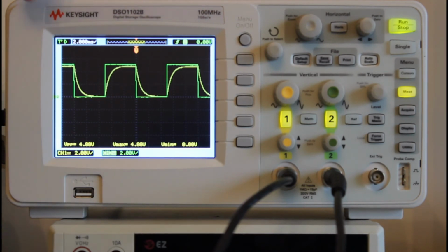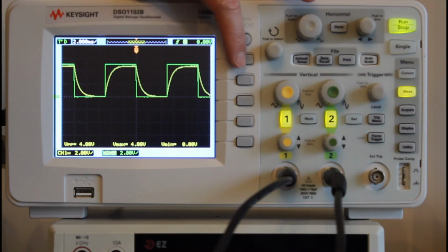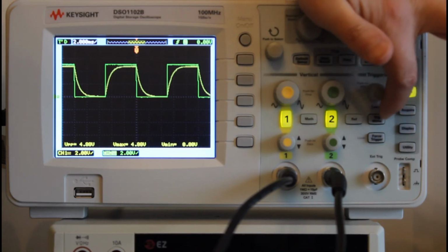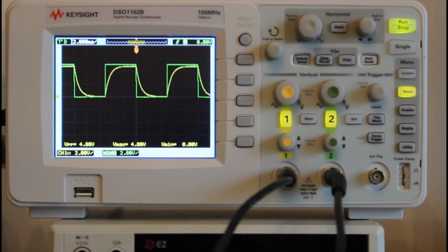To get this pair of green and yellow curves, the input and output of the RC circuit, one thing you need to keep in mind if you do the experiments yourself is when to press the trigger manual. Then choose the trigger to the edge, and it's a rising edge from the slope soft key. Remember that if you start to do the experiments yourself, it will be readjusted again by the lecturer.